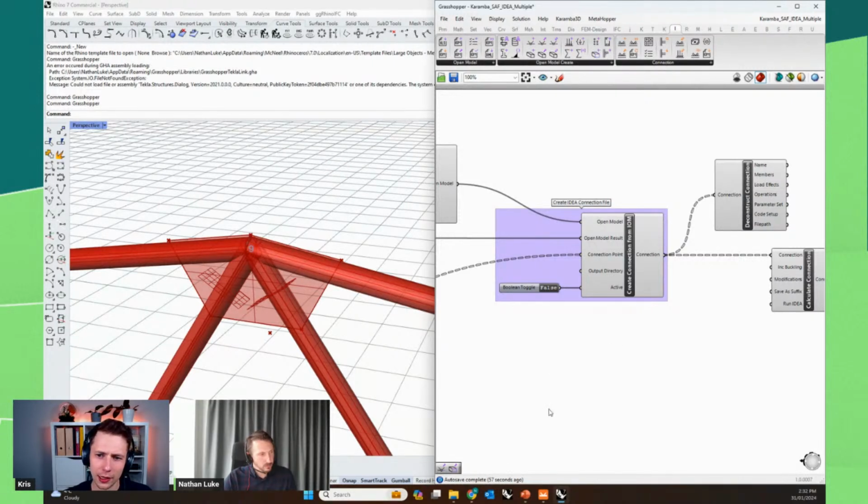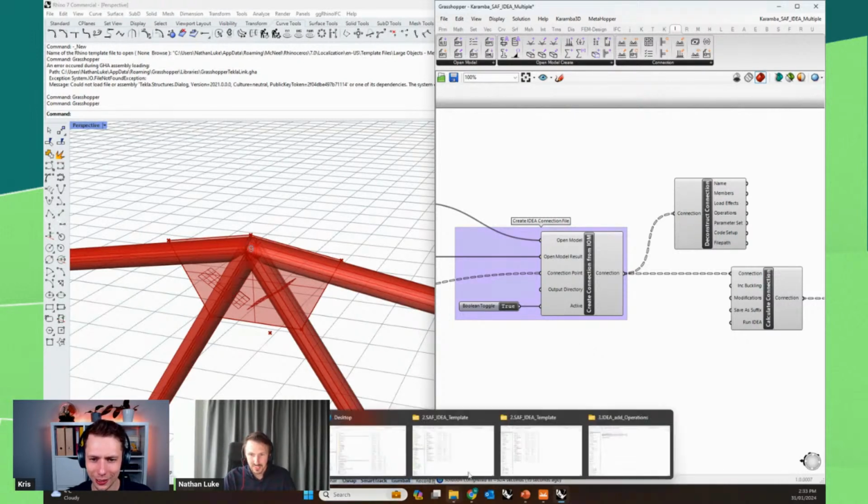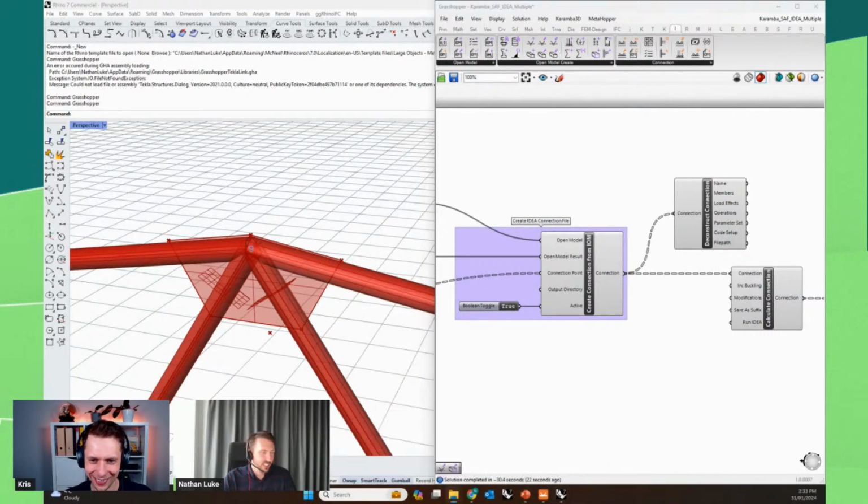So basically speaking, you can just generate this plate with all the cuts, all the welds, and send it directly to IDEA StatiCa. When you do it manually, I can imagine that it's lots of work with all the cuts and the welds. And I imagine that if you change one of the angles of one of the steel members, you have to do everything manually again. Exactly. If a member size changes, you have to readjust the plate, based on the weld length based on the size of the cross section, or the plate positioning as per the incoming member.